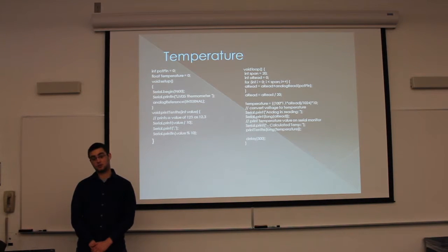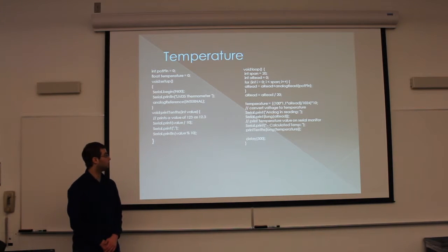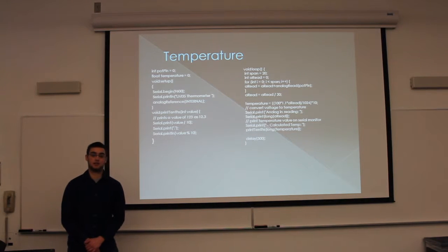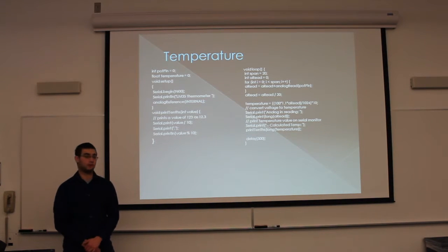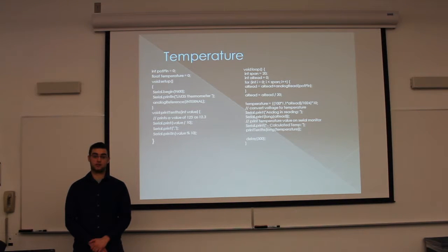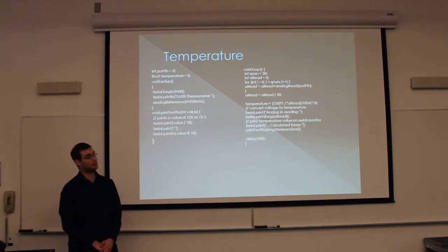So this transistor is measuring the voltage drop due to the temperature of the room. And what this does is this conversion, all this multiplication, and what that ends up giving you, like I said, is a number 10 times the degrees Celsius of the room. This can be found out by knowing the temperature of the room and then figuring out what it's reading, and you can actually do this by taking several points. And this is a conversion that was given to us.